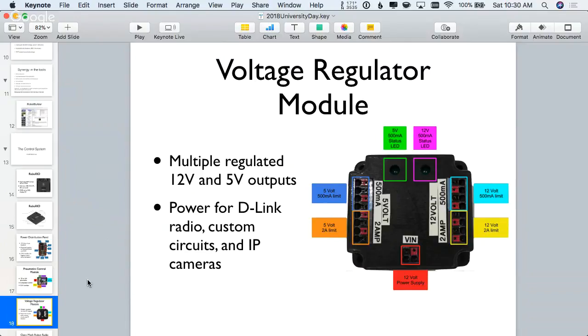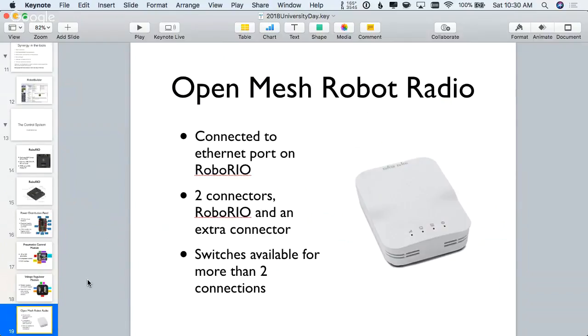They're very good if the battery voltage starts sagging. You have to connect your radio to this because it's a 12-volt supply for the radio. If the radio browns out when you start drawing a lot of current on one of the motors, then it loses communications with the field, and the radio takes like 40 seconds to reboot. In a 2-minute match, going away for 40 seconds is really annoying. Talking about the radio, yeah.